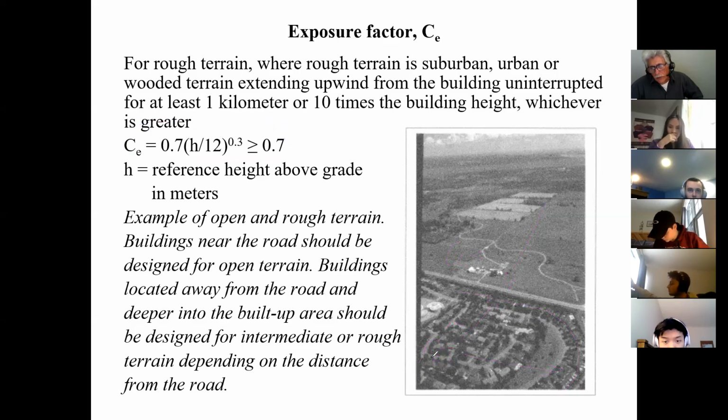So I hope you guys can see this. This is just to give you an idea when to use rough terrain. If you're not sure, use open terrain. That's the safest thing. If you're absolutely sure, then you can use rough terrain, and it's going to reduce your pressures a bit. That's all it's going to do.